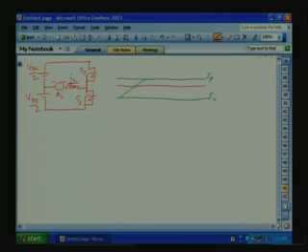So the load current will slowly decrease. Again the moment it comes here, again we are turning on. So it will go like this. So the rising slope and the falling slope need not be equal. The falling slope will be faster because EC is opposing. EC plus VDC by 2, both are opposing. So this is the current ripple.